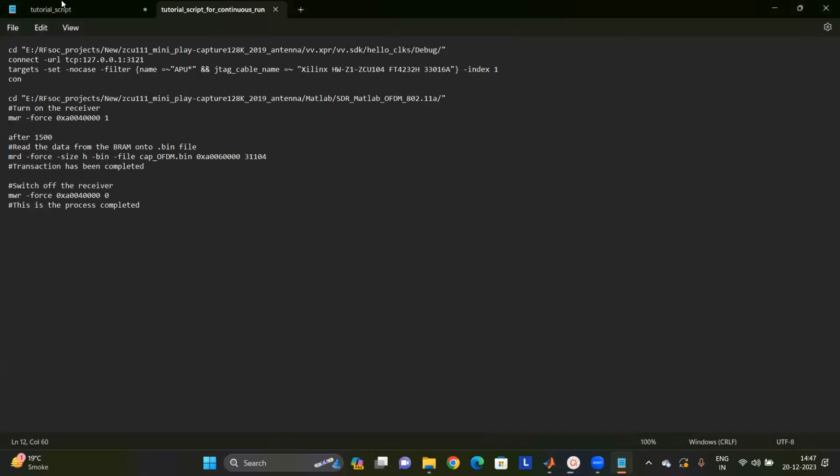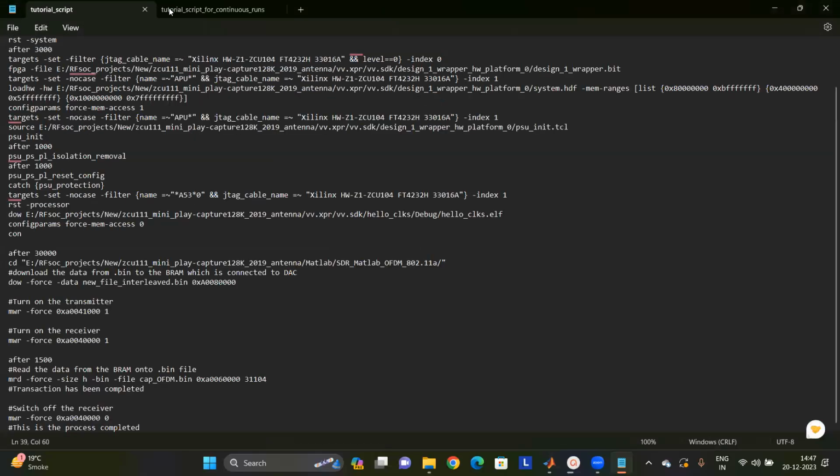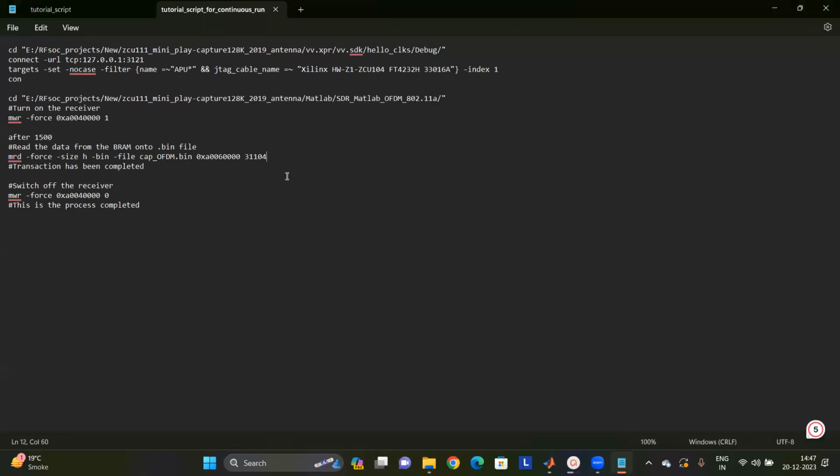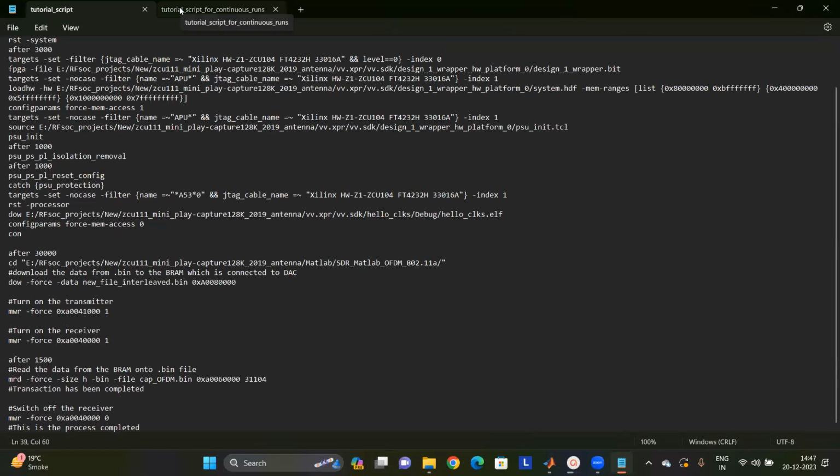Now, the reason that I have chosen 31,000 samples is because for 31,000 samples, I have 15,000 complex samples. Now, if you remember, I needed to have at least 3 frames in one processing window. If I go below 15,000 samples, that will go to nearly 12,000 samples. Then there is a probability that in some window I might have 2 frames or even fewer. So in order to avoid that situation, I have kept at least 15,000 samples. So in every processing window, I have at least 3 frames to work with, so that I have enough data to process.